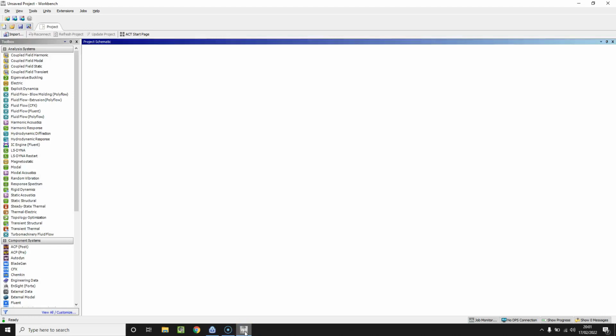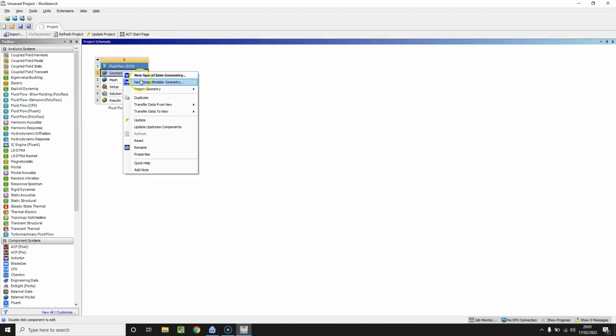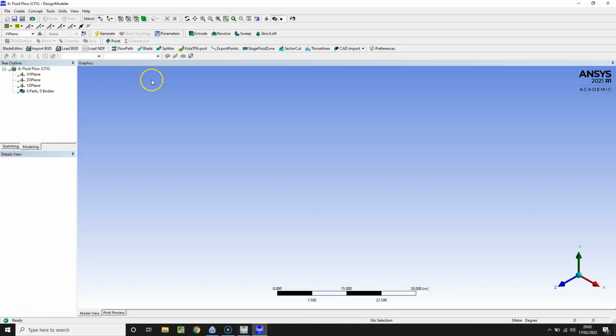In this short video, we're going to do some HVAC simulations where we look at the heat transfer from our radiator into the room of a domestic house. So first of all, just grab Ansys CFX and drag it into the workspace. And right click on geometry and hit new design model geometry.